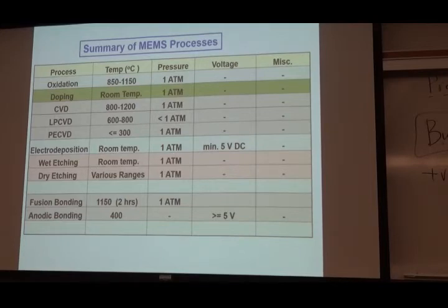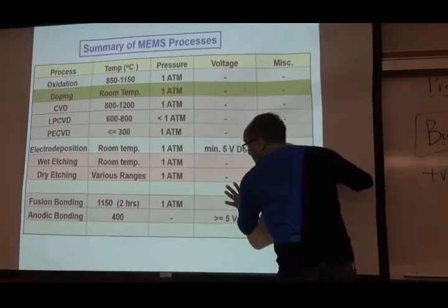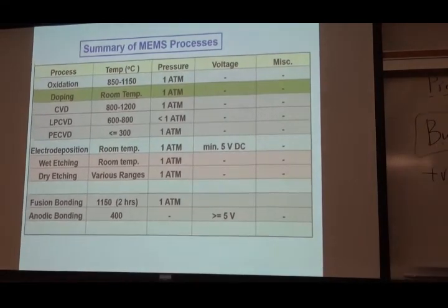It takes about overnight to reach 10 to the power minus 9. So if you want to do your metal deposition, you do a little prep the previous night, keep the pump on, then it automatically takes over. You guys will see it in our facility. After a while, the molecular pump will take over. So this is a very important table to be completed.